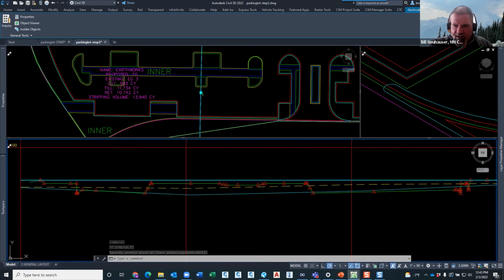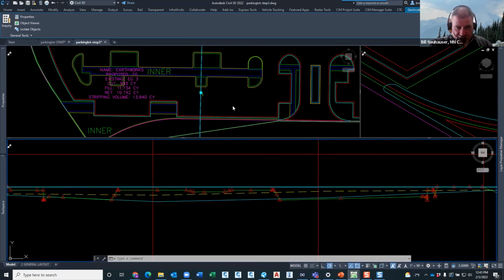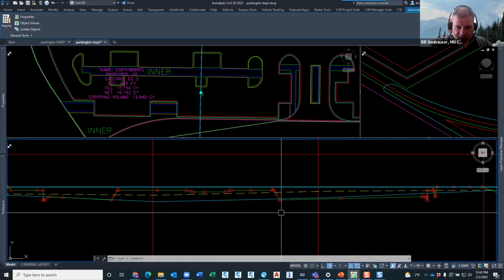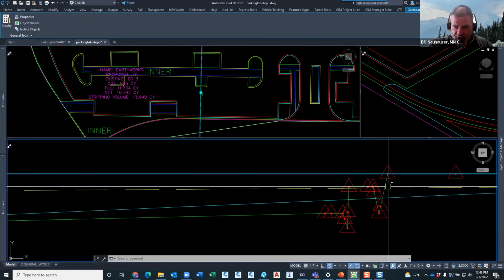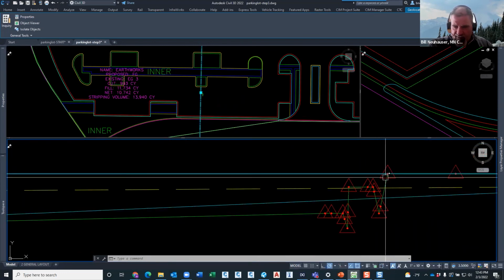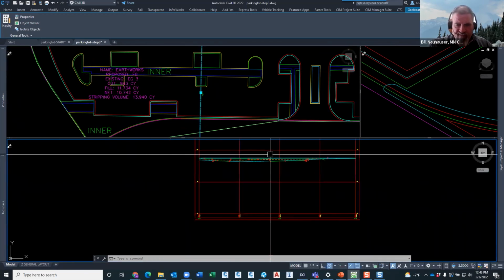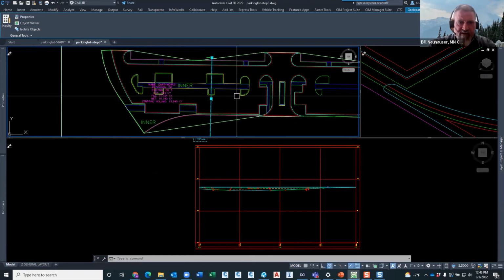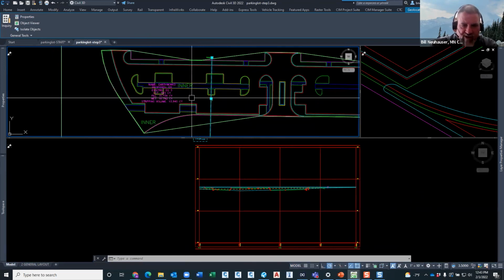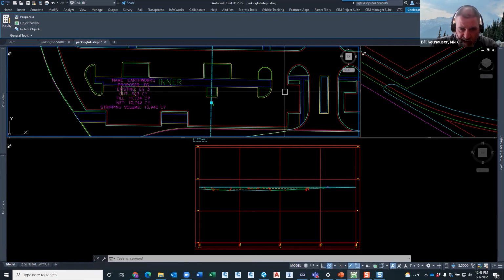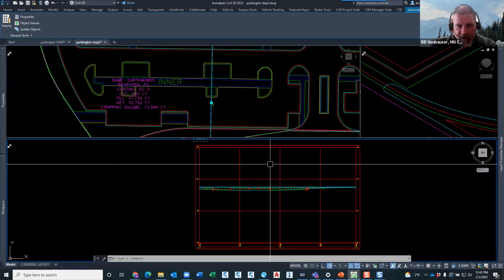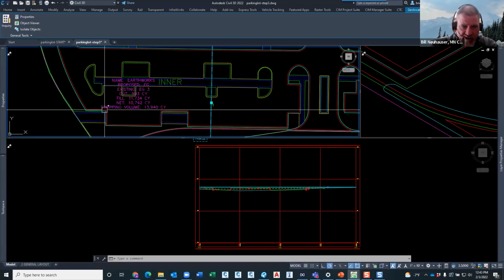Okay. It might look a little better if I actually had a finished ground surface out here that had the curb line drawn in. You know, the curb here is going to look funky because yes, I'm going down 2.5 feet and coming back up to the 1.49 feet. But you get the idea. Now, again, my objective here was to show you guys how to get this stuff set up. Actually running this stuff, again, that's another training class all by itself. I'm just trying to show you how to get your drawings ready and what to look for.